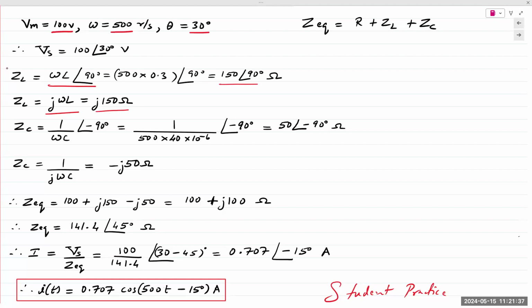The question being asked is, what if you had a current source in there? You would just proceed exactly the way it is. No. If it's a current source, it doesn't have anything to do with the inductor itself. The inductor by itself has an impedance angle of plus 90. Whether you apply a voltage or a current does not matter.